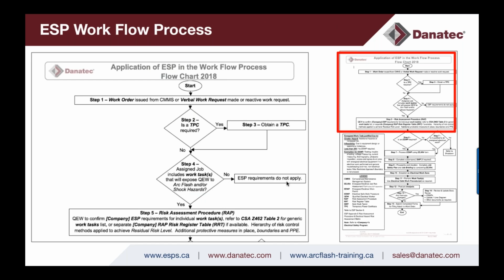So TPC stands for, is a temporary power certificate required? The answer is yes or no. Now that relates to, again, construction and installation of large generation and power distribution on a temporary basis. If the work order doesn't require that, the worker goes to step 4, and then they review the assigned job. They determine that it includes discrete energized electrical work tasks that may expose them to arc flash and shock.